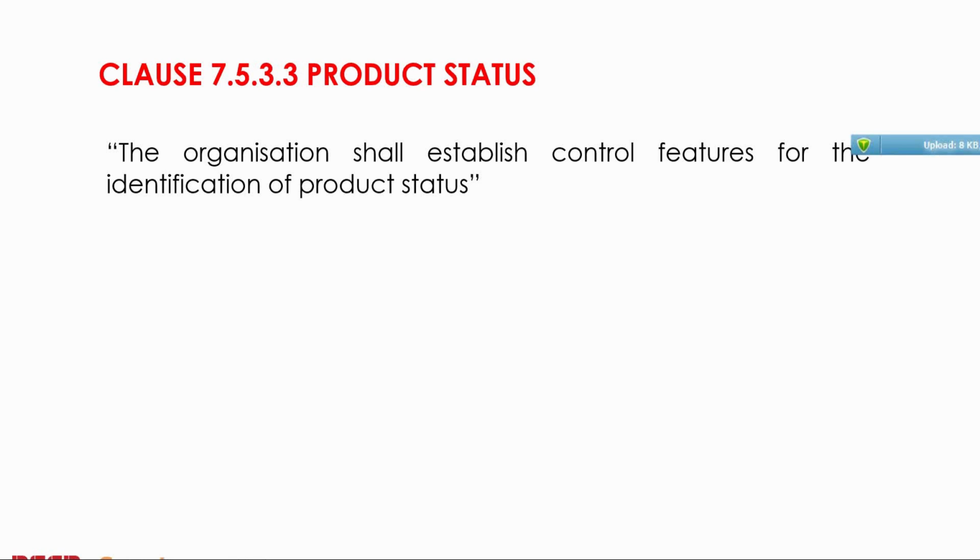In 9001, the inspection test status is within the clause on traceability. In process inspection points, etc. Often this is done by means of a traveller outlining the process along with the inspection test operations the product has gone through.